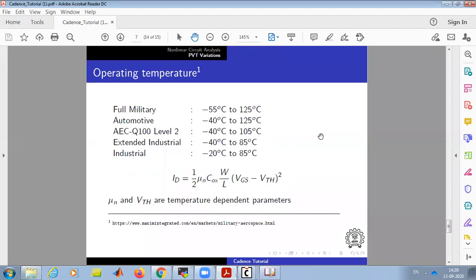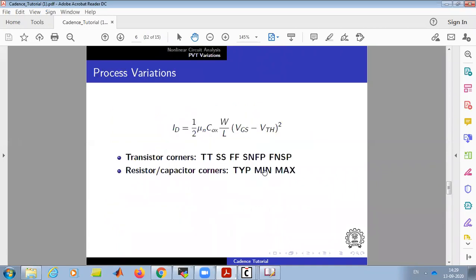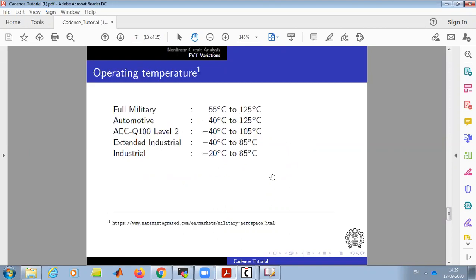So whatever circuit we design, we need to take care of all this: process, voltage and temperature. If you see the combinations, if you have a single resistor and corner, you will have 5 process variations and 3 voltages, so 15 cases, into 3 temperatures, 45. So there will be hundreds of simulations you need to do. You cannot sit and just tweak it 100 times. So there is one provision in Virtuoso which we'll use, and we'll see how we do all this process corner simulation.